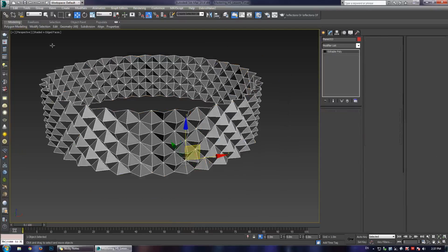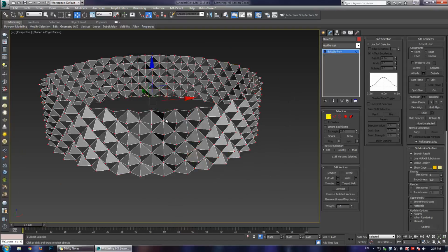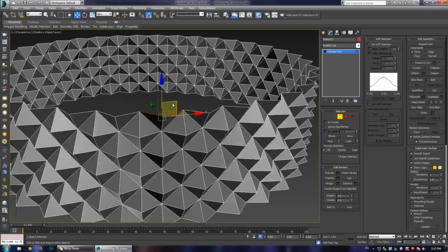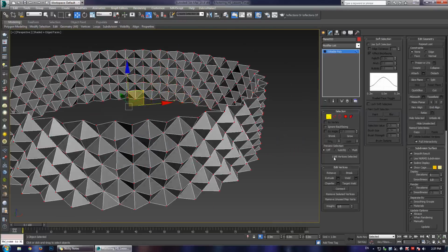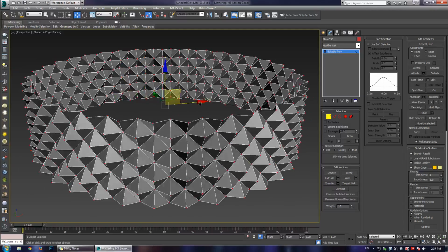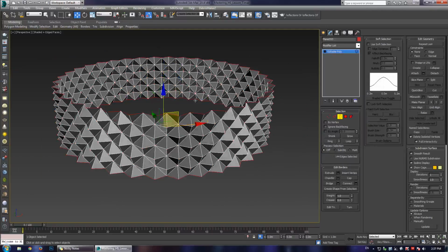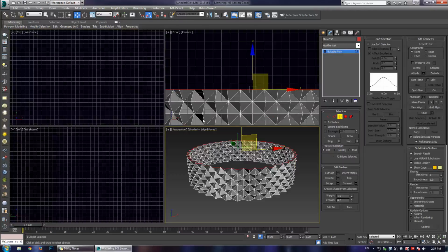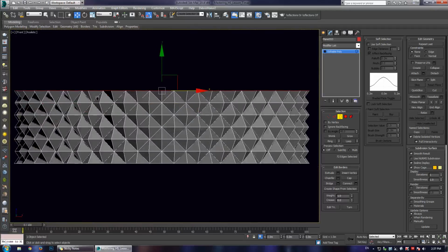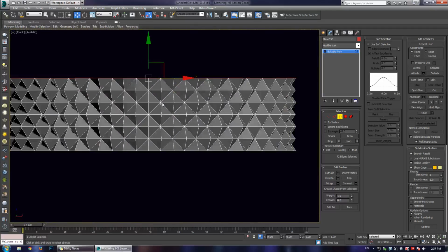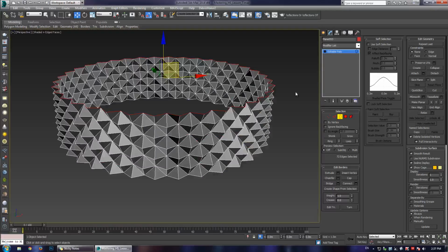The next thing I need to do is go in and select all the vertices, because you'll notice that we haven't snapped any of these. These are all single elements. They're not actually attached together. So I'm going to go in, attach those. You should be able to see the before and after number here drop. And now we're ending up with 504 vertices. And all those borders, the only borders we've got visible are up the top here. So at this stage, the next step is to go in and add the hardness to these so that when we smooth it, it's not turning into little blobs. So I'll just show you there.